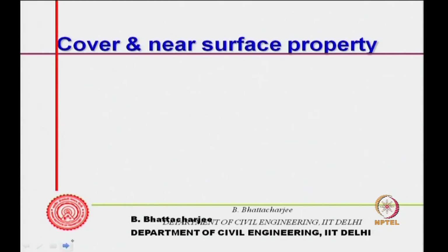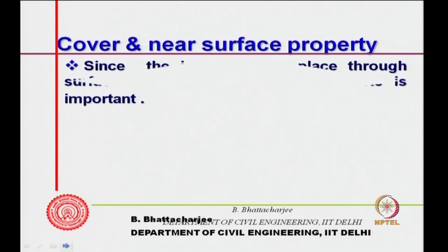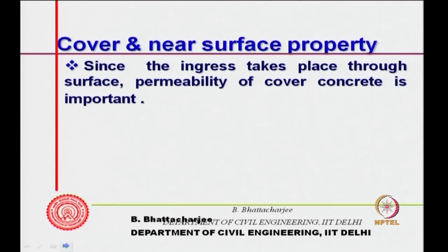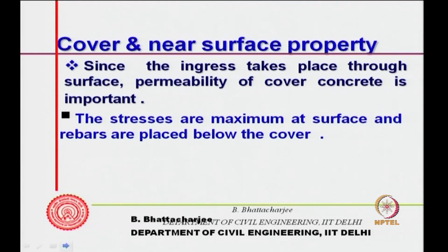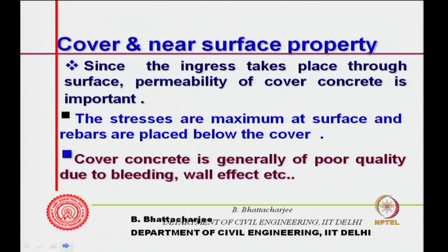Anyway, this is the situation. But one more important issue is, for durability, cover concrete is most important, because ingress takes place through the surface. So, permeability or permeation property of the cover concrete is important, and all in situ measurement of course looks into the cover, because that is what is approachable. But you see, the stresses are maximum at the surface, and rebars are placed also below the cover. So, importance of cover concrete is very, very important. Cover concrete is generally poor quality due to bleeding, wall effect, etc.